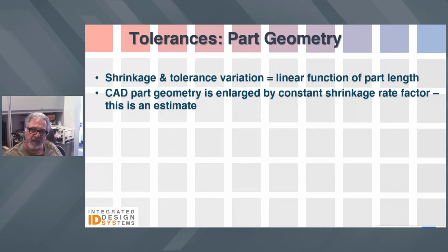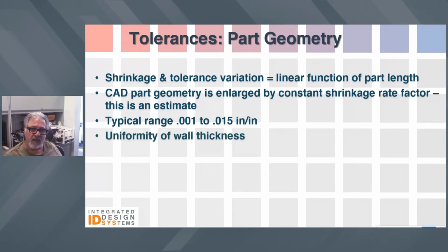And once that's experienced, the parts are now molded fairly consistently if the processing conditions are maintained from part to part. So it's that initial shot that is critical. And as mentioned earlier, the tolerances can range anywhere from plus or minus a thousandth to as much as 15 thousandths of an inch per inch, and that's quite significant. Typically, the olefins tend to have that higher shrinkage rate.